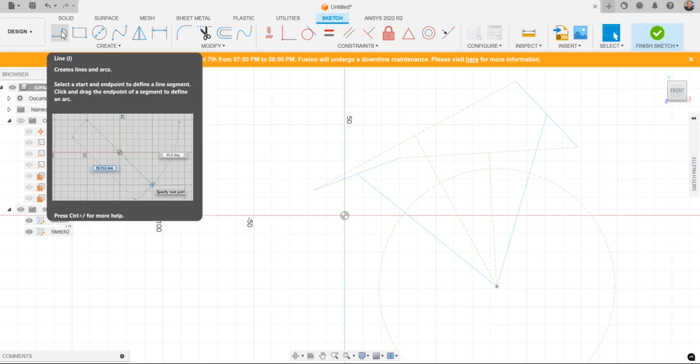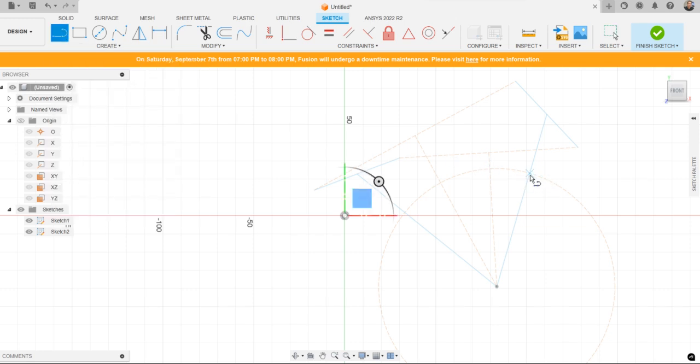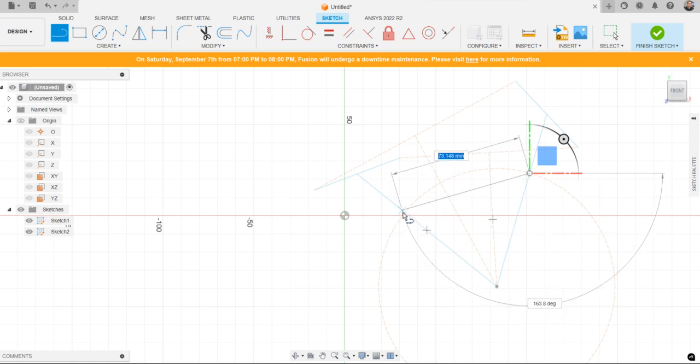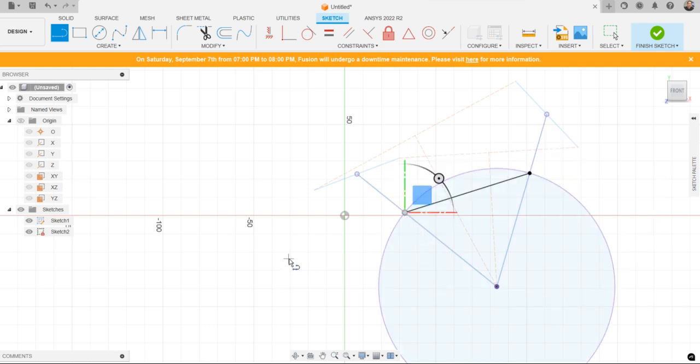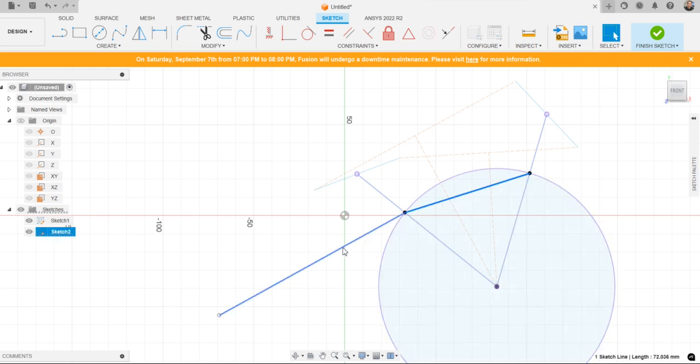Okay, so what I will do now is to create the line that joins this. Actually, I can try to continue this line, but this time I couldn't, so no problem at all. I will continue from here and I will try to create it parallel to the first one. I will tell the software that these 2 are reference lines, and then I will use the parallel constraint telling the software that these 2 lines are parallel.